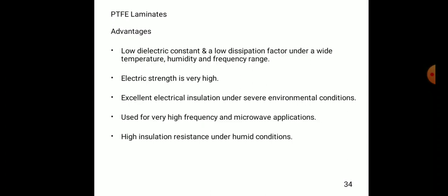High insulation resistance under humid conditions. That's why we are using the polytetrafluoroethylene laminates very frequently. The disadvantage of these is that the high costs rule out their widespread use. Because of the very high cost, we don't use this type of laminate frequently.